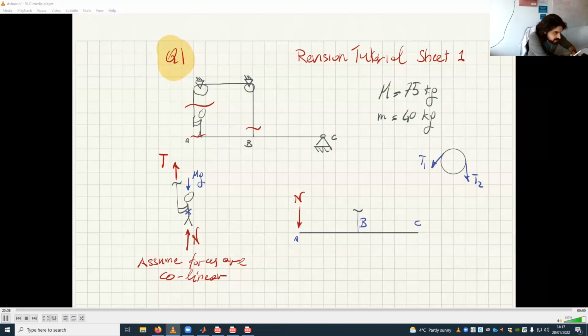It's the same under certain conditions, okay? Because it's the same if the pulley is massless and frictionless, and the cable is inextensible and massless. So in this case, imagine if you have a pin here. So if I do the equilibrium around Z, so around point O in the Z-axis,